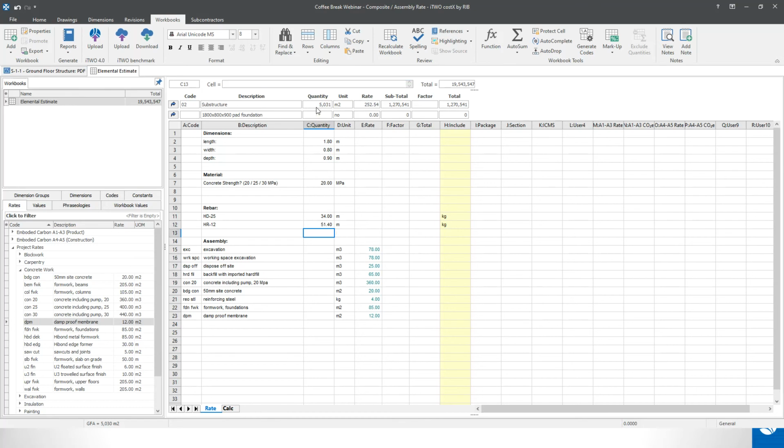We can now hit the Enter key to complete that formula off. And we've got the total length. My mistake, I've actually got this the other way around. There we go. So now we've got the total length for all of these stirrups. Perfect, so we've got the lengths for each of these different types of bars, and now we want to go ahead and apply a factor to those lengths to convert it to kgs.